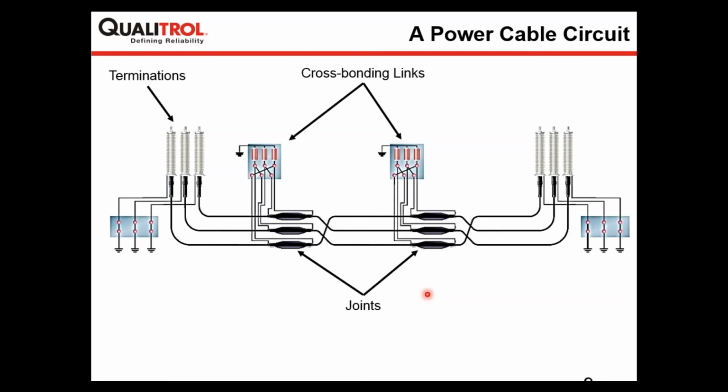If you contact us later on, we can give you the literature or discuss in detail how to perform this return time measurement and how to accurately get the PD pulse propagation speed. Based on these two pieces of information, the cable length and the propagation speed, and the time difference between the main and reflected pulse will give you a very accurate location of the partial discharge from the measurement end.